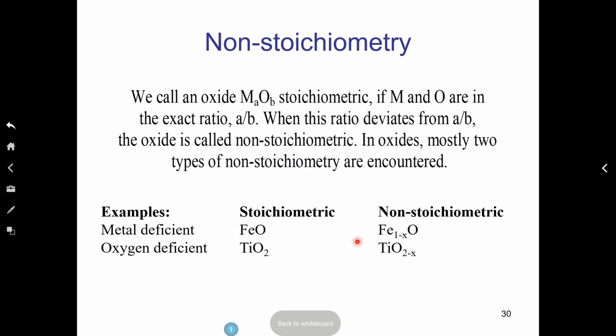If you introduce some non-stoichiometry mechanism, cation vacancies, then you will convert this insulator into a semiconductor. So there are materials like iron oxide, cobalt oxide, nickel oxide, and a few others that will create non-stoichiometry on the metal sublattice. And it's done by control of PO2.